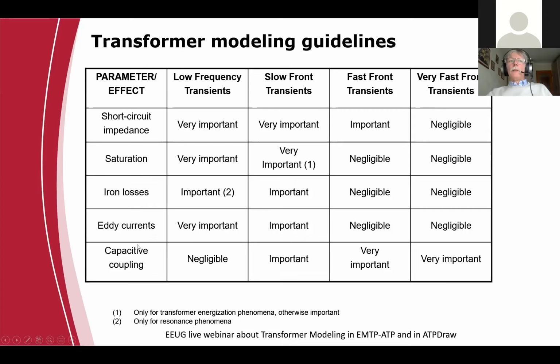The capacitances between the windings to the tank or interwinding capacitances are not so important. This table tells we can omit them. It doesn't mean that you can omit them completely. I never suggest to replace these capacitances with 0 capacitance. If you have no idea, use 1 nanofarad, 2 nanofarad, or in that range.